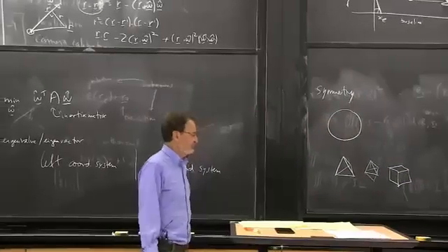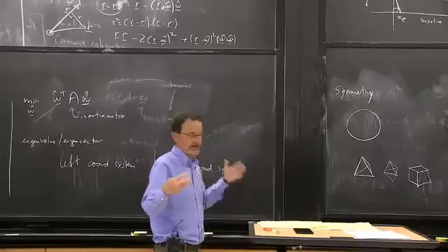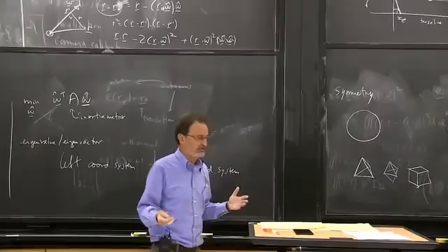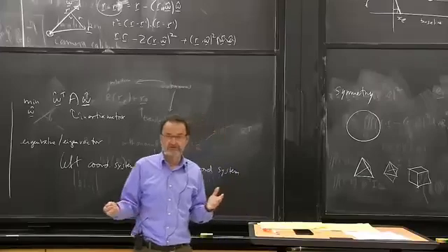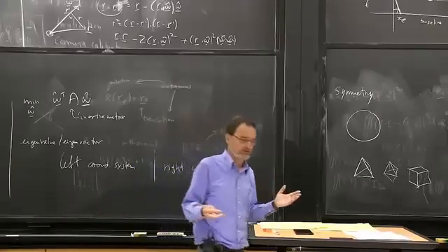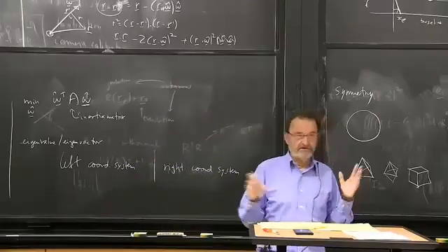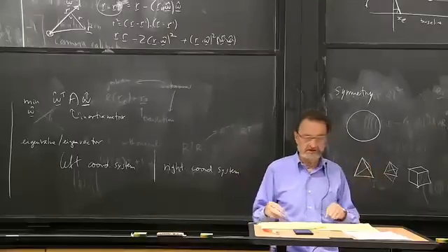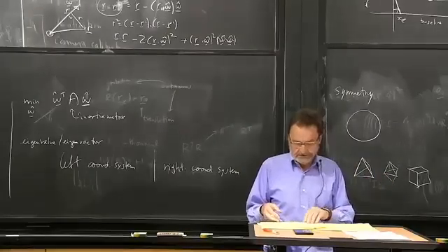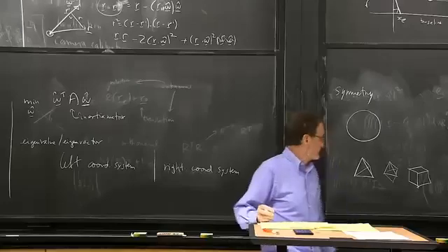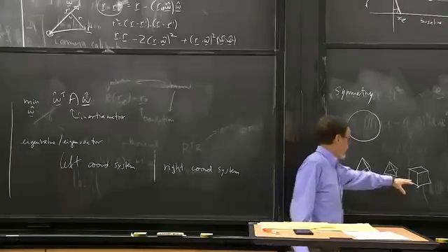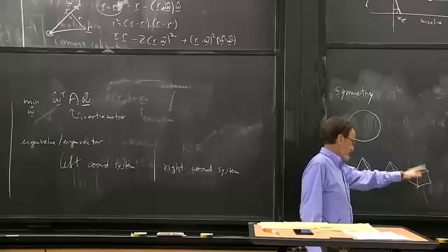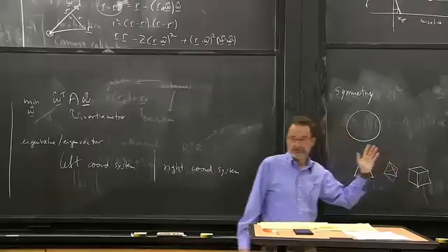Now, you'd think with a cube there are three well-defined axes. So what's going on there? Well, the trouble is that the inertia about those three well-defined axes are all the same if it's a cube. If it's a brick, then you're fine, because the three axes will have different inertias, and you can line things up that way. But with a cube, again, somewhat surprisingly, you can pick any axis, you get the same inertia.